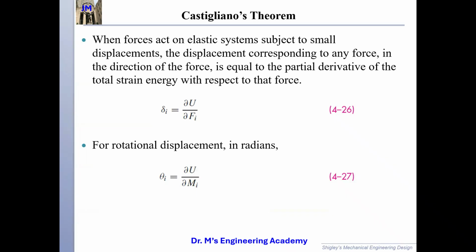The difference between the energy method and the partial differential equation method is that we look at the energy of the whole system. The underlying assumption is that the structural system reaches the state of equilibrium when the energy of the whole system reaches the minimum.